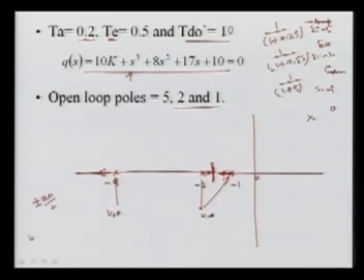It is decided by the point where we can draw the axis, which is decided by all these poles divided by 3. So minus 5, minus 2, minus 1 divided by 3, and it is nothing but your minus 2.3. So that value we are taking as 2.3, and now we have to decide the angle. The angle will be 60 degrees here. So these 3 axes will be there, and from 2.3 here, this will be leaving at 90 degrees, and then this will be changing.